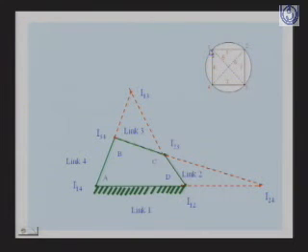So you just see that we have located here 1, 2, 3, 4. This tells you the number of links. It is link 1, link 2. So if we have already located the instantaneous center between 1 and 2, this is a firm line. So this is telling you about this instantaneous center. The instantaneous center between 2 and 3 we have already calculated, this one, so it is a firm line. Similarly 1, 4 and 3, 4 are also firm lines.